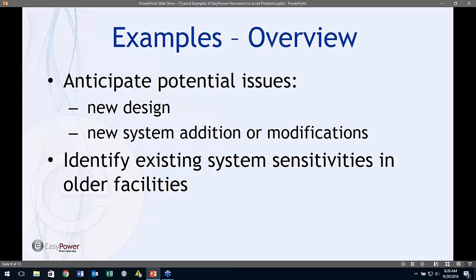What I'm going to do here is a real quick overview, a snapshot of a system, and isolate or potentially focus on areas that could have problems just based upon the data we collected during an arc flash study. So it's a starting point. It's a point to have a conversation with the client because he knows, or they know, where they have harmonic sources, and therein lies the challenge of trying to close this loop.